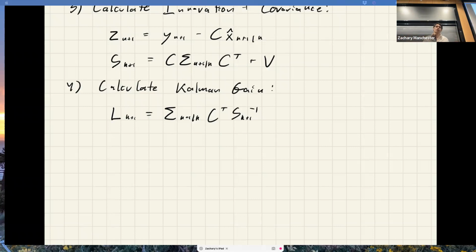That's a legit scenario for a particle filter, where you would assign probability over the map and you might be in three different places. But then as you move around and collect more data, you start to coalesce around one. So that's a real application for this that does get used in practice. So there are situations where you have to do it. But in general, if you're trying to know where your robot is, or the state of your thing, and you really don't know and it's this kind of multimodal blob, you're in deep trouble and you probably need more sensors.